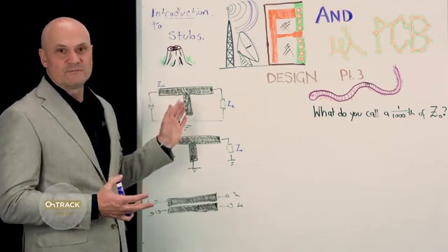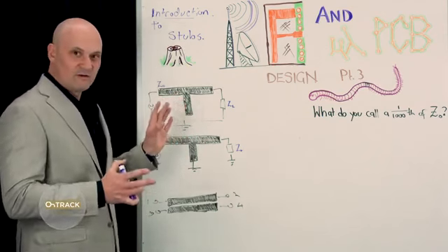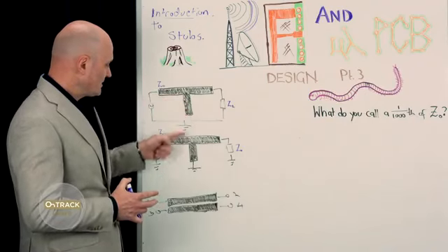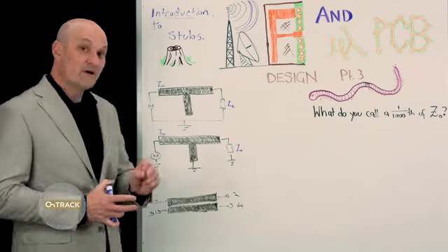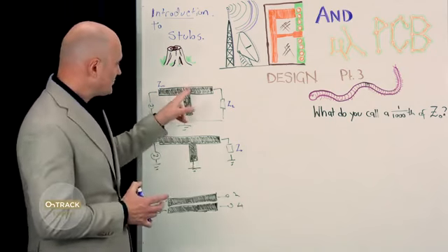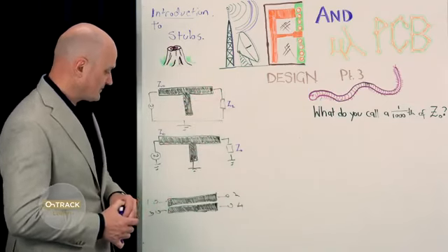Now it could be terminated resistively or capacitively, but almost always it's going to be an open circuit or a short circuit to ground, or maybe a power supply. We'll look at those cases, and then the transmission line carries on to the load impedance.